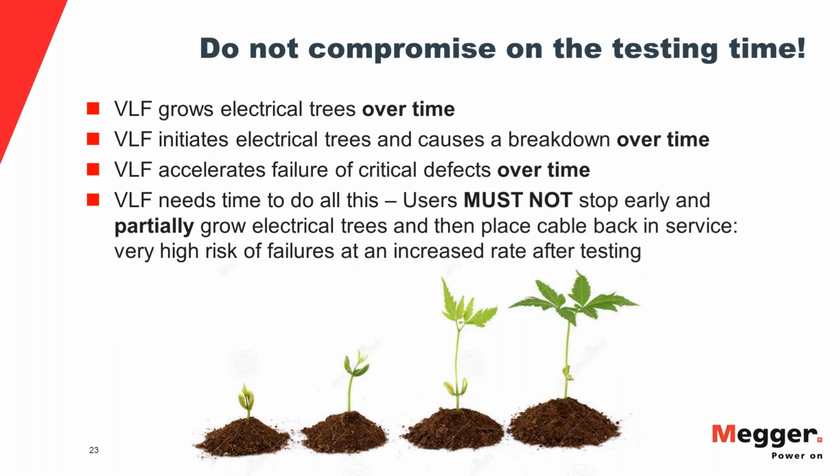So one other comment, because you saw in the one table 60 minutes, 30 minutes, whatever you do, never compromise on the testing time. Because once you apply the VLF voltage, it is stressing the insulation, and the water trees are sitting there, and then electrical trees are formed, or existing electrical trees are accelerated.